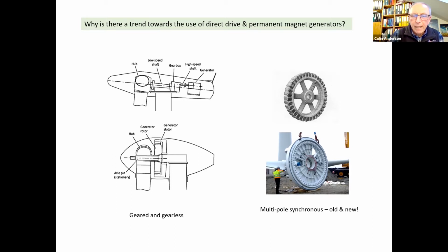And I've actually illustrated within the book. There's a couple of illustrations here. One is the difference between a high-speed generator, which requires a gearbox between the wind turbine rotor and the generator, and in this case would be an induction set. And here, a low-speed generator with multi-poles, which is connected directly onto the rotor, and this dispenses with the gearbox.